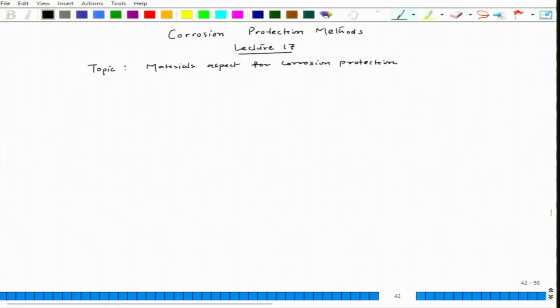After alloying a little bit of platinum or palladium in titanium, initially both dissolve, and then because titanium has a much lower reduction potential than platinum, the platinum would redeposit back and form some sort of deposit on top of the titanium metal. Then the hydrogen reduction reaction will come into the picture, and it will take it to spontaneous passivity. So those are the aspects we have talked about.